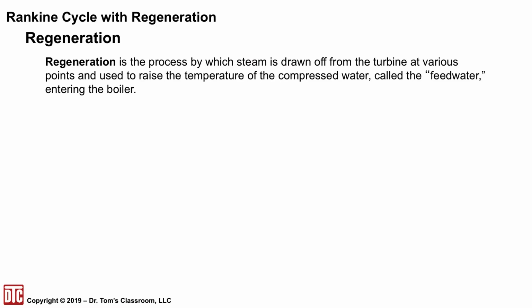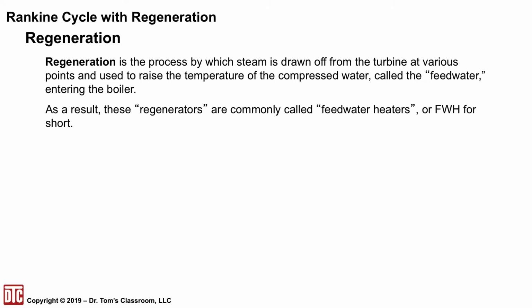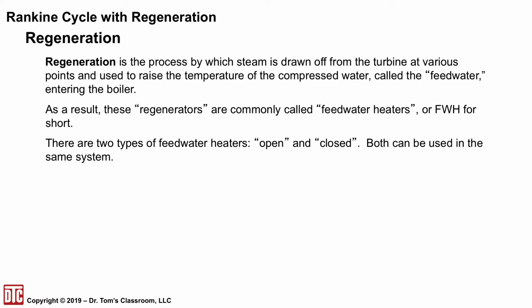Okay, regeneration is the process by which steam is drawn off from the turbine at various points and used to raise the temperature of the compressed water, which is called the feed water, entering the boiler. As a result, these regenerators are often called feed water heaters, or FWH for short. And there are two types, open and closed. Both can be used in the same system. However, the reference handbook only has a picture of an open feed water heater in its cycle.